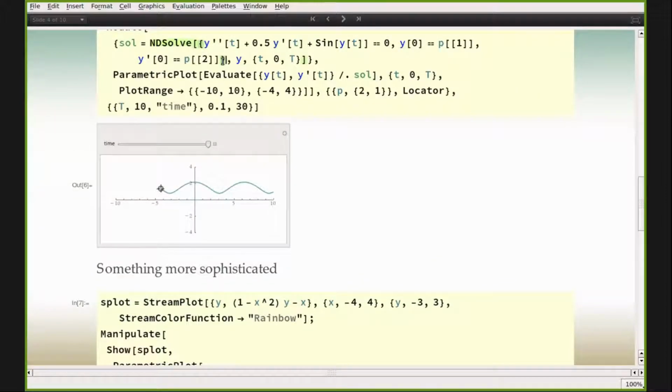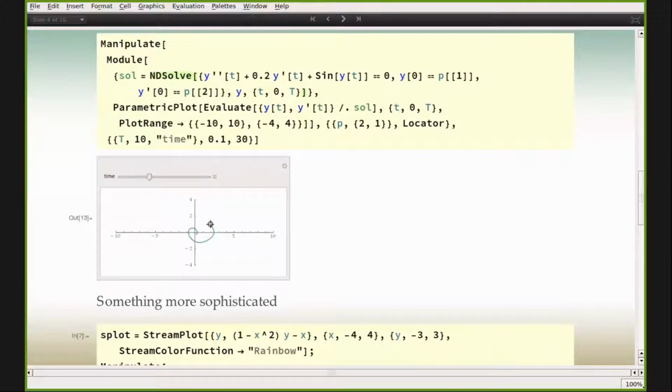So let's try to compute it. I don't know if this friction is quite large, so maybe let's make a little bit smaller friction. Okay, so now you can see that starting from some point, the oscillations disappeared because there is some friction which consumes the energy from our system, and finally the system stops. As you could see previously, you had these sinusoidal oscillations.